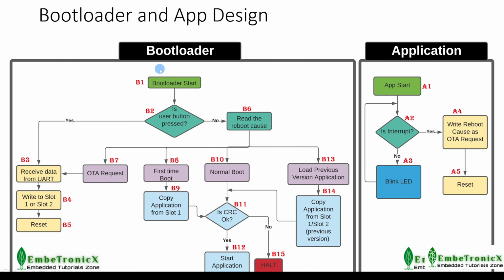Let's continue to the bootloader. When the bootloader starts, it fetches the stack pointer value and stores it to the MSP. Then it jumps to the reset handler of the bootloader, followed by the main function.